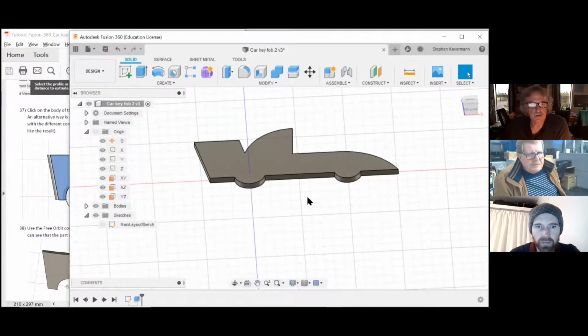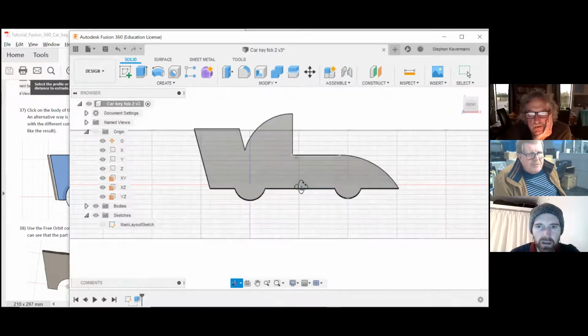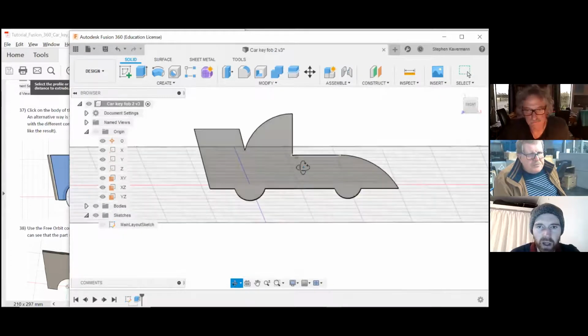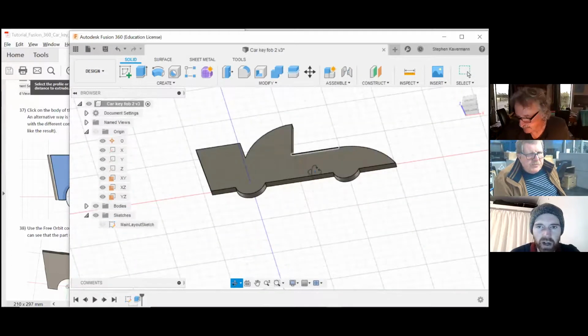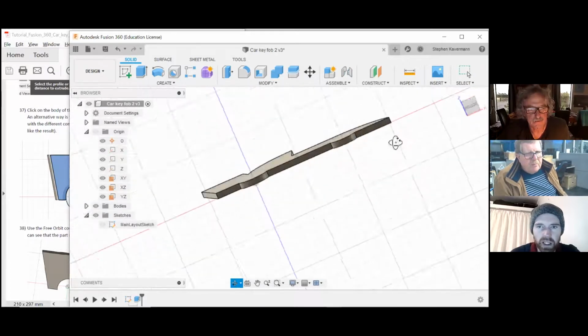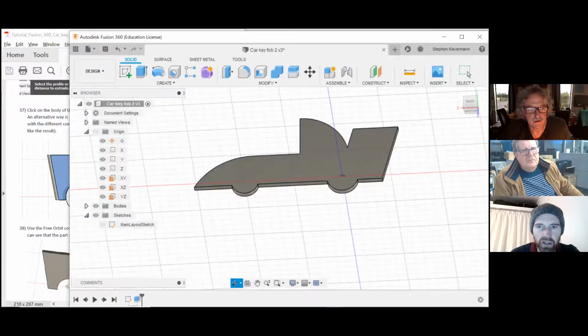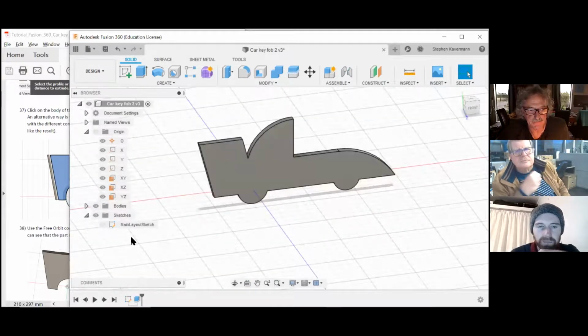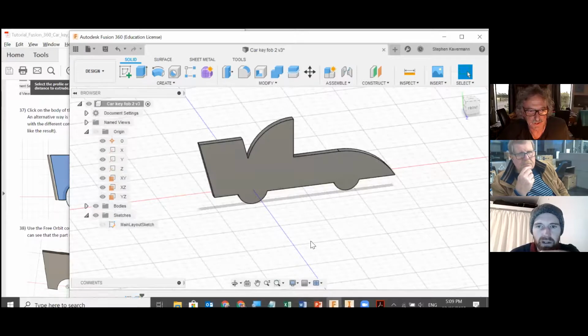How are you rotating that? Oh, sorry. To rotate to see 3D, you hold down Shift and then hold down the middle mouse button and then drag around. It'll probably take a little bit of getting used to. Each CAD software does this in slightly different ways. I've used a lot of 3D viewers, and it's very similar, isn't it? It's like flying with a joystick that's backwards. Yeah.